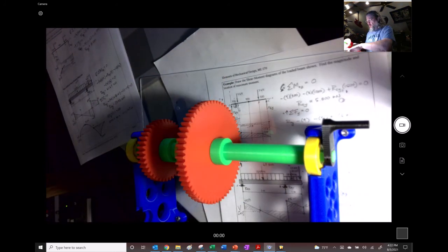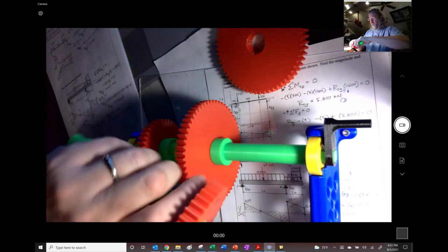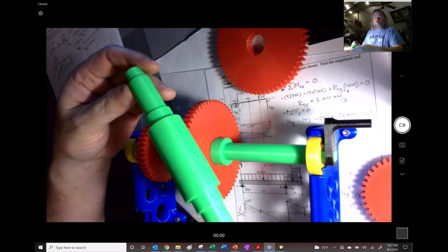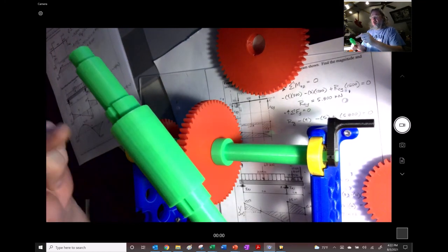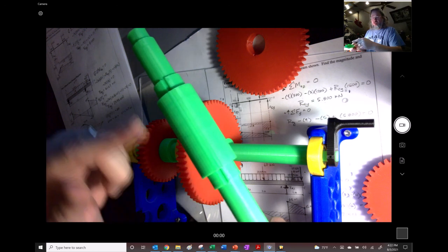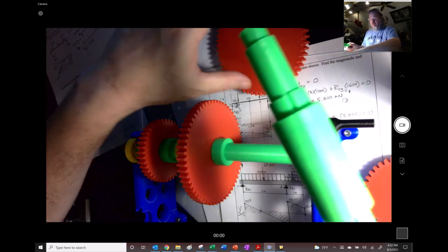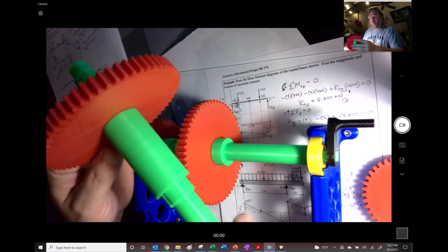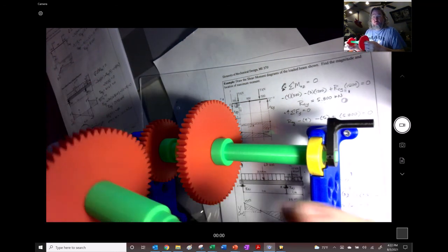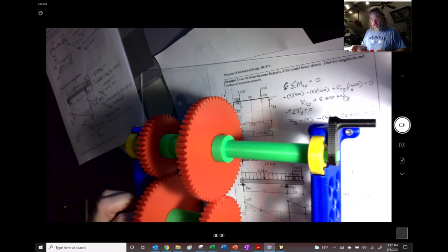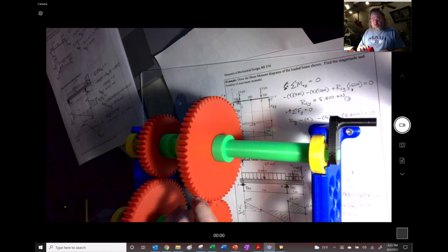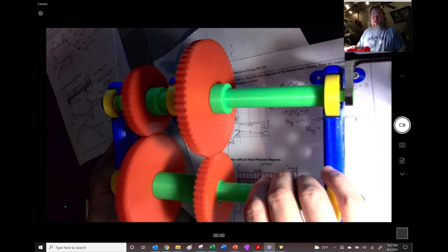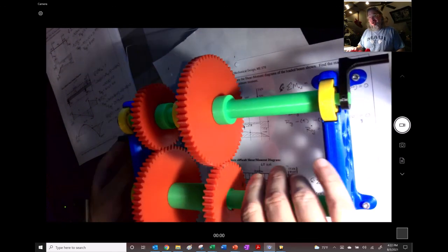So we want to look along the length of the shaft, where we often ignore the gears, and try to figure out where it's loaded with the most moment. Chances are, most of the time, it's at one of the gears. We don't necessarily know which one when we're starting out, but over time we can see a trend, because we're going to do this problem over and over again. That's usually where there's going to be the most stress. We'll be able to predict where this thing is most likely to break, and then we can decide how big we need to make it.